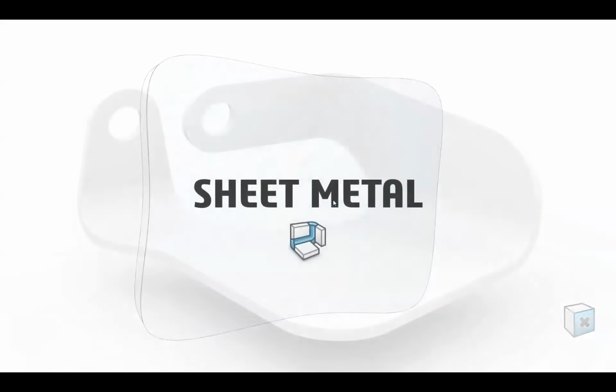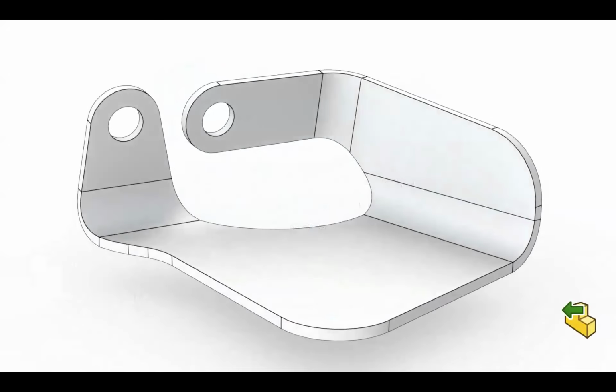You want to get rid of the fillets and add your own? Great, delete face. Get rid of that. You want to recreate the boss? Great, delete face. Super easy. For sheet metal, you can take something that's been imported, and I'm going to show you a couple of these examples. This is just for a little preview.